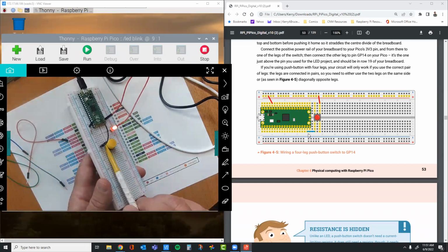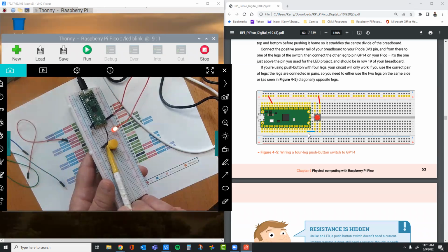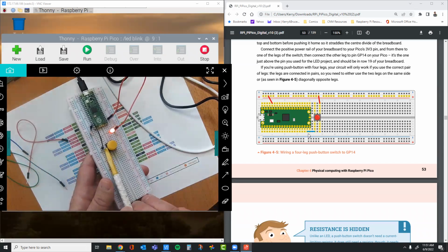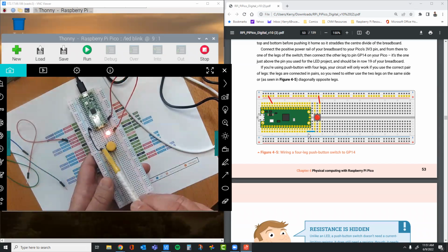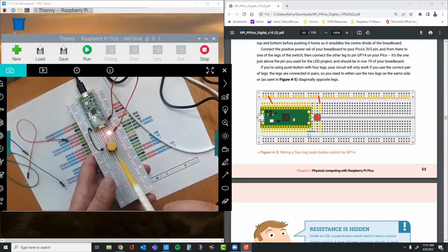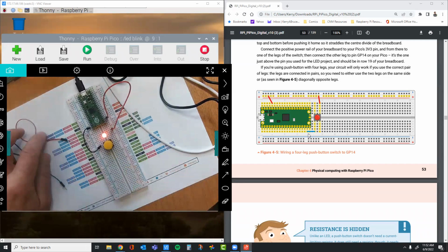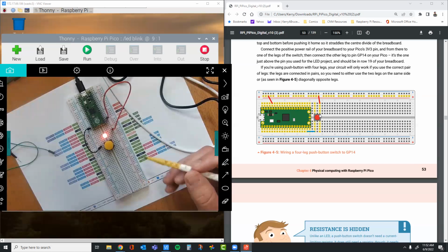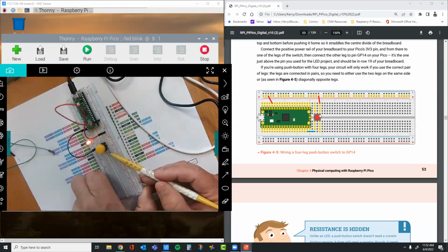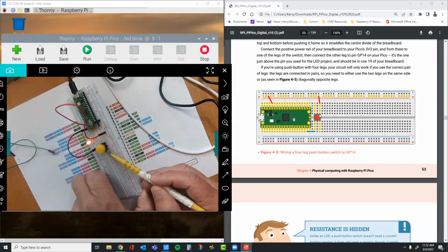Right down here, I can see that my little metal pin is right at the tip there. It's in this row, and I've connected this wire to the same row. So now that pin and this wire are the same thing, okay? The other side of this needs to go to power. I'm going to connect to this pin way over here on this side.